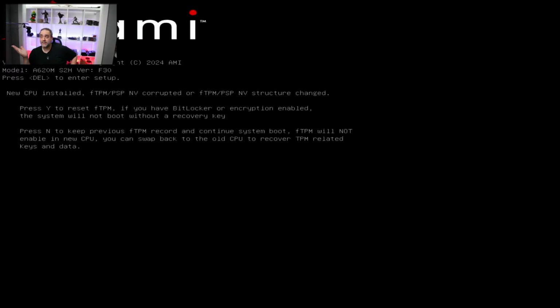I had a feeling this processor's not supported on the first BIOS. All right, this happens sometimes. We're going to use Qflash-plus if this is. I'm going to give it another minute because AMD is really slow. The new processors take a long time for that memory training to happen, and sometimes the boot sequence is literally a minute. So let's wait about a minute just to be sure. See? Look. Okay, see, it supports it. But you see, I was already doubting myself. All right. Anyway, let's move this over to full screen.